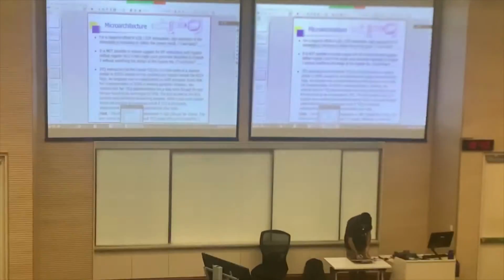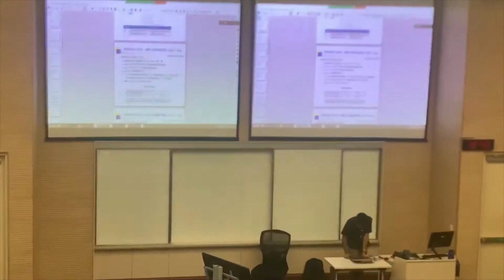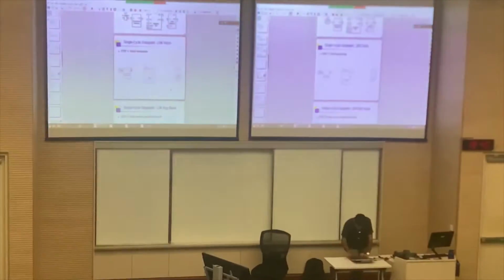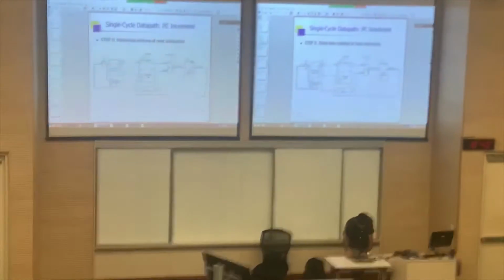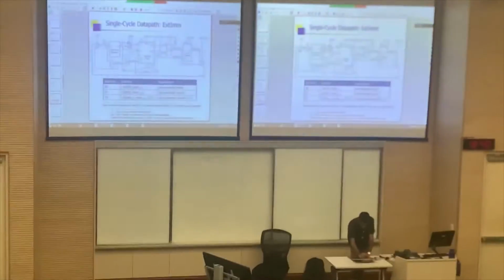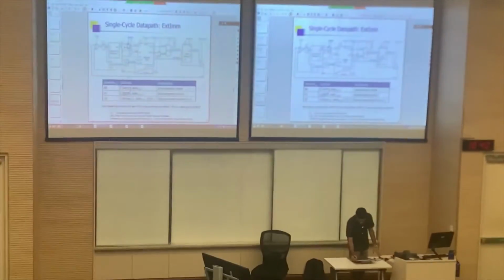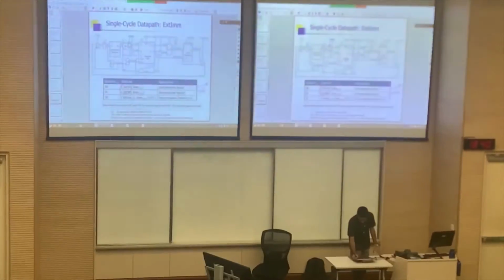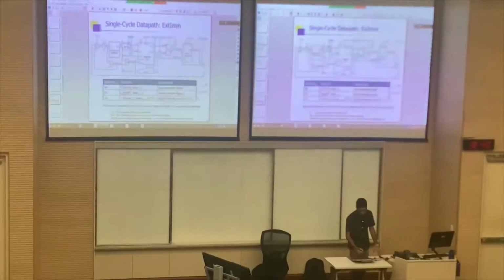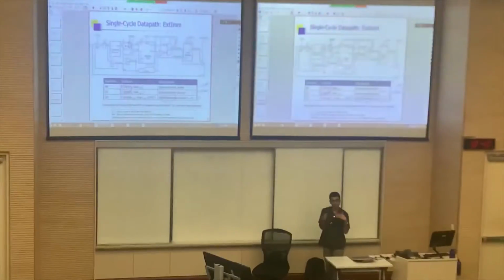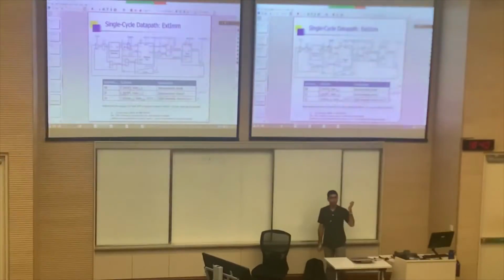You can see it here. Here, you see, it's a 0 extension for DP as well as memory. Only for branch you do sign extension, because the immediate for a branch can be positive or negative, it's a signed quantity.